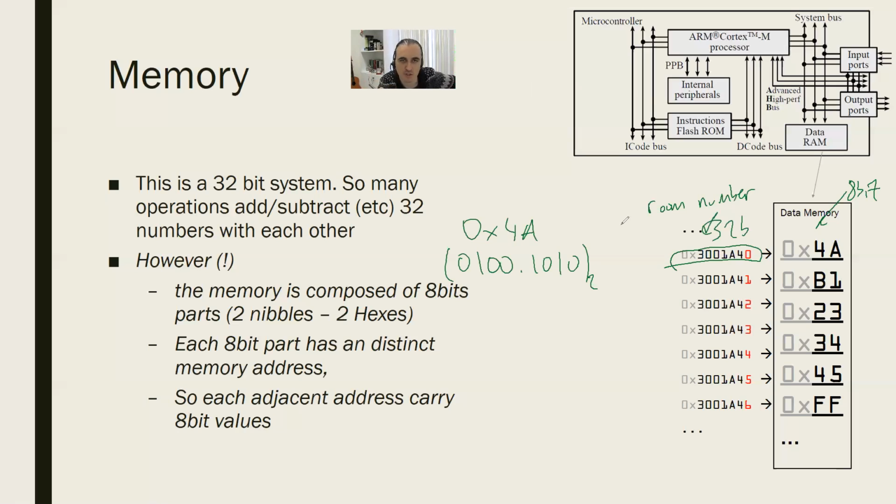So regarding your question, imagine you want to keep a 16-bit value. For example, let me write a code here. Sorry. Imagine LDR. No, let's say that this is STR. We are going to do these examples, but I'm going to be doing this for you. For example, you remember what this code does? You have a 32-bit value inside R0. You get the value inside R0, which is 32 bits. You're writing it to somewhere in the memory, which R2 points to.